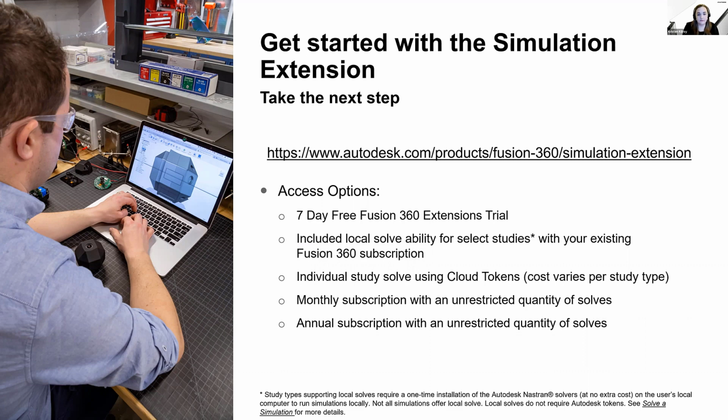If subscribed to Fusion 360, as I mentioned earlier, you already do have access to that local solve option for some of the studies. It's very limited with the number of studies, and it includes static stress, modal frequencies, thermal steady state, and thermal stress. And it is restricted with the amount of solves that you can do at a time. So look into it before you do rely on that, because you might need additional solver capabilities.